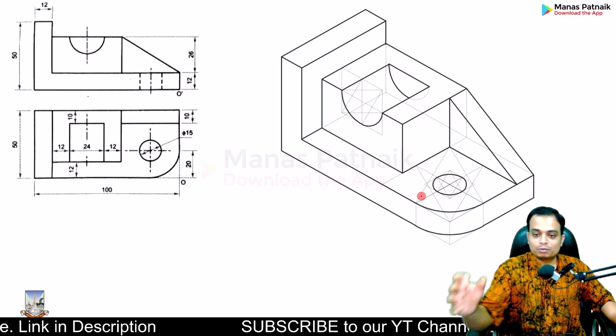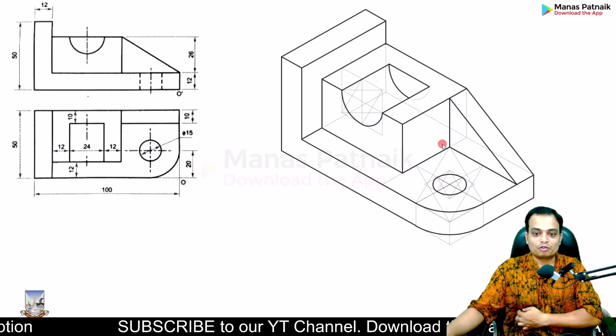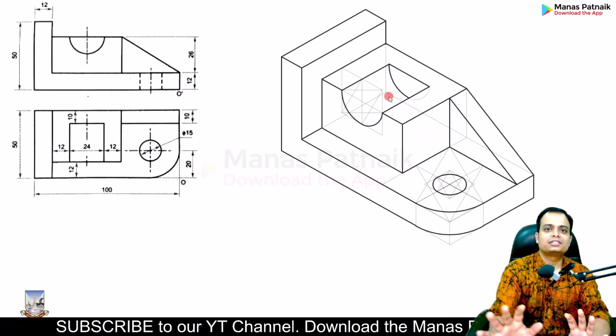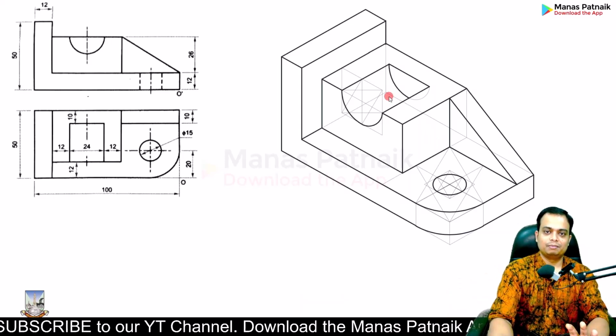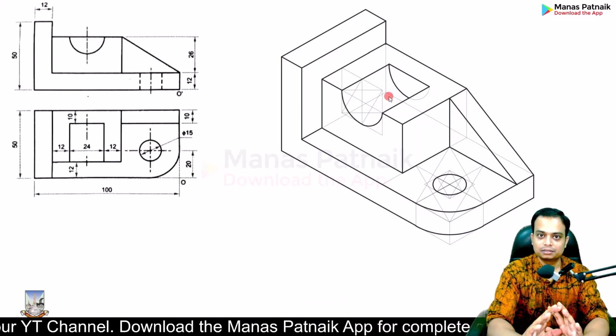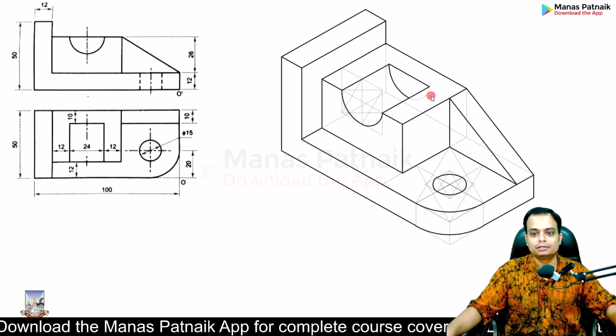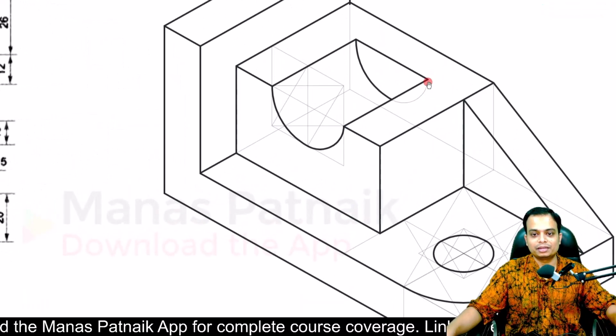If you are taking so much pain to construct these circular and semicircular profiles, make sure the construction stays. But use a very, very light pencil, 3H or a 4H pencil for that purpose, right? If you do that, everything is going to look very decent and sophisticated.